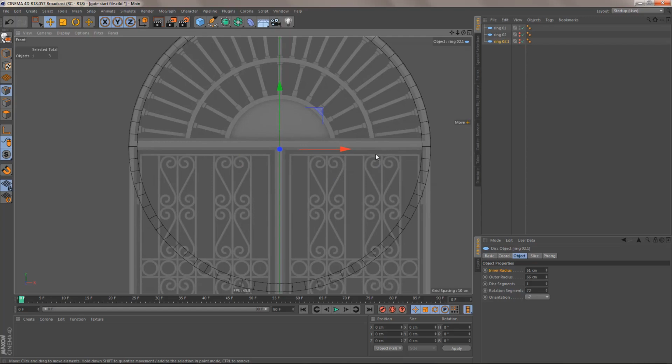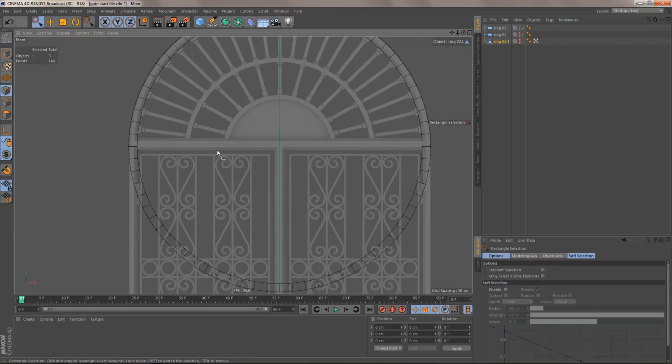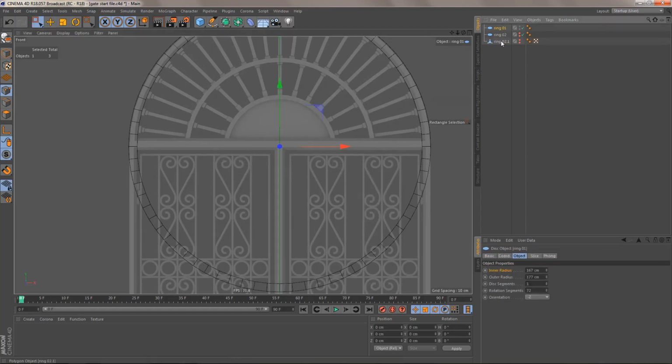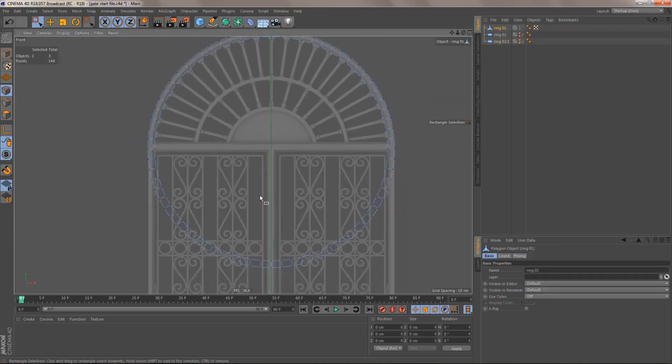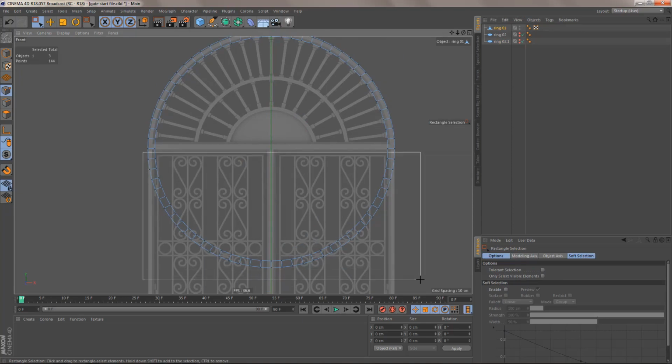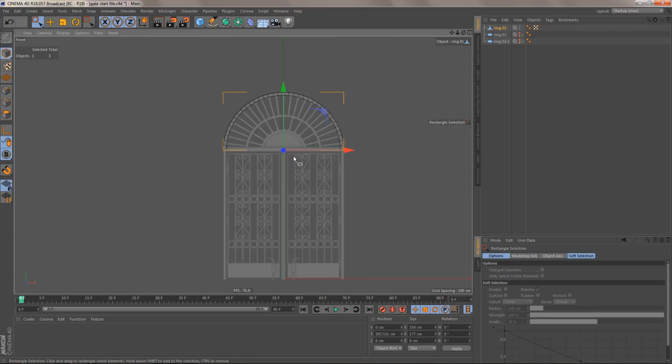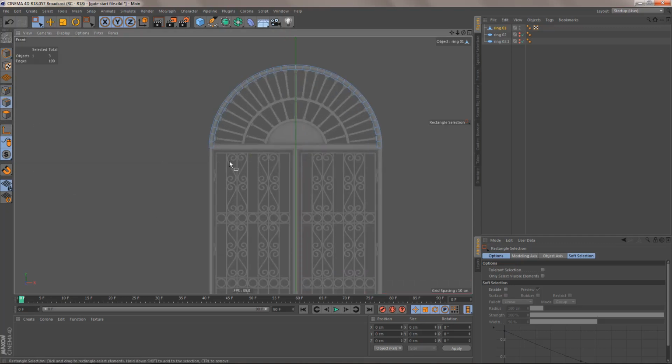I'm going to make this editable, and we can... I made the wrong one editable. So ring 1. I'm going to delete the bottom half, and let's go to model mode, and I'm going to move the object axis to the bottom here. And let's go back to point mode, or maybe edge mode, and I'll select these edges and extrude them down and move them to 0.